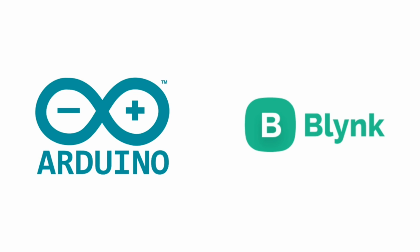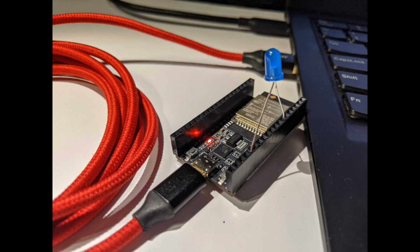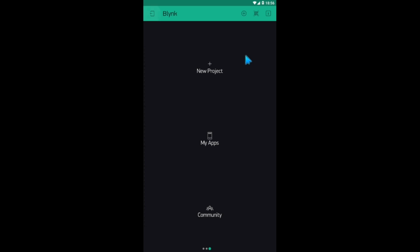You're also going to need to have the Arduino IDE installed on your computer and the Blynk app installed on your mobile device. You'll need to connect the LED to your device. Positive, which is the long leg, goes to pin 2. Negative, the short leg, goes to ground. It'll look something like this when you have it done.